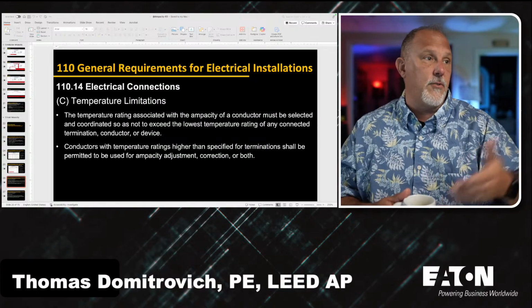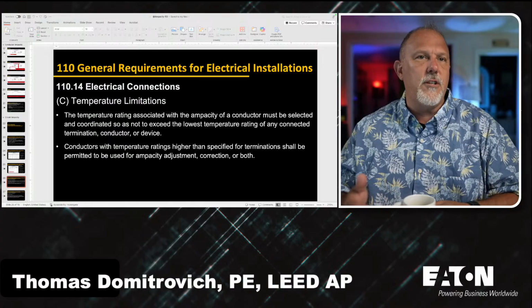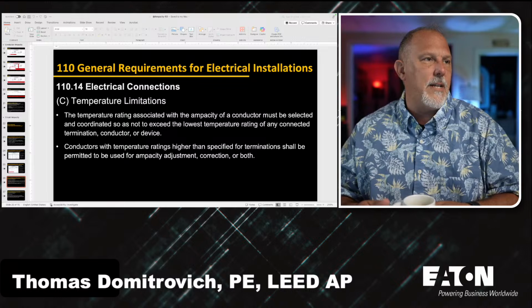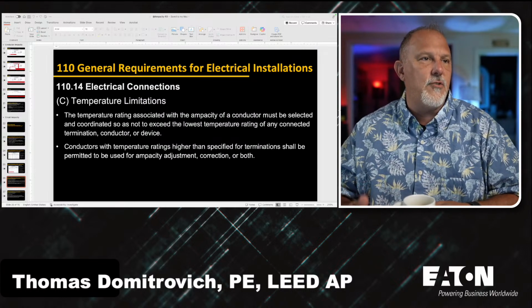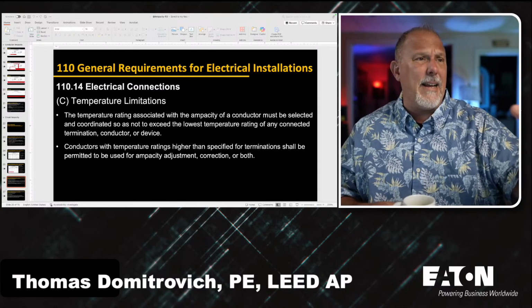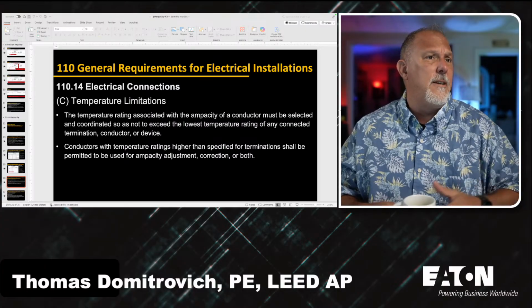There should be dissimilar metals. There should be 110.14(A), dissimilar metals. Anyway, conductors of dissimilar metals shall not be intermixed. There's just too much in that parent text. And then it says connectors and terminals for conductors more finely stranded than Class B. So there's a fine stranded. So they got so much in the parent text. Those are requirements that should be in first level subdivisions.